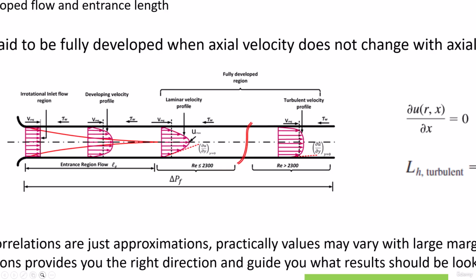And in this case, the velocity profile is highly different. It has sharp gradients on the wall, very, very sharp compared to the laminar flow. But in the middle region, there is a maximum velocity, but it is flatter than in the laminar flow. And the maximum velocity varies like 1.2, 1.1 times the average, depending on the Reynolds number.